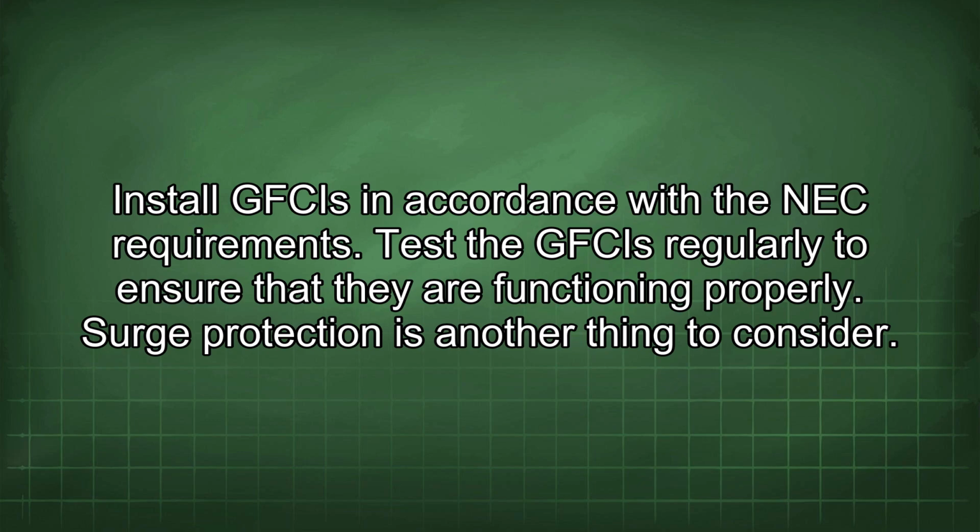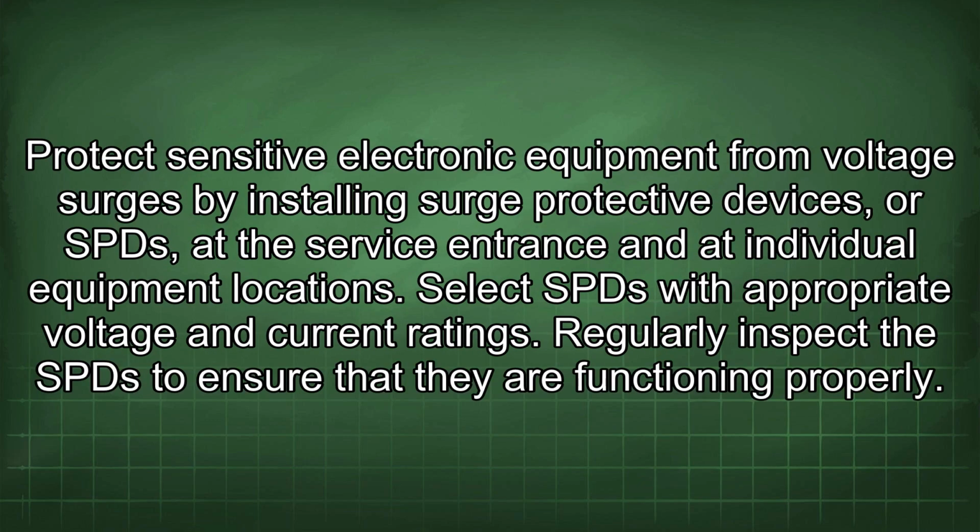Surge protection is another thing to consider. Protect sensitive electronic equipment from voltage surges by installing surge protective devices, or SPDs, at the service entrance and at individual equipment locations. Select SPDs with appropriate voltage and current ratings. Regularly inspect the SPDs to ensure that they are functioning properly.